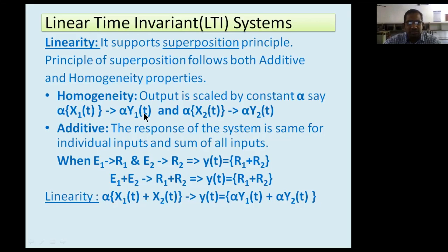That is called attenuation. Now, if you apply another signal of 20 volts, then proportionately that much change has to occur in the output signal. Here, the input has been divided by 2. If you apply 20 volts, the output should be 10 volts. If you apply 40 volts, the output should be 20 volts. That means the scaling factor always remains constant.